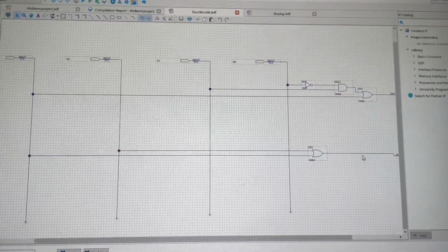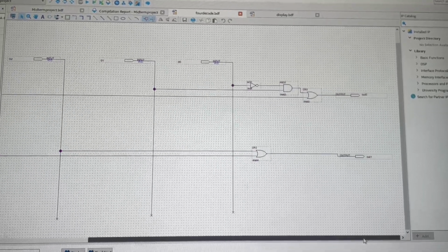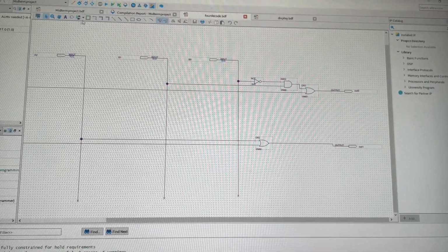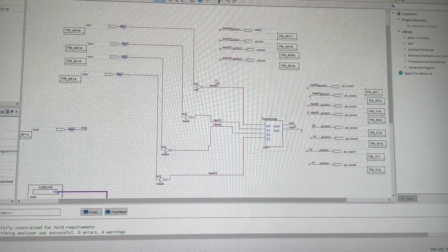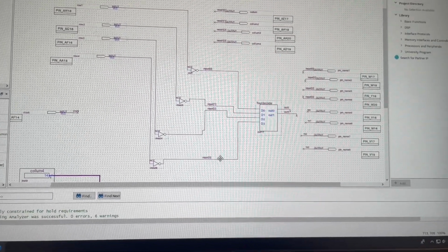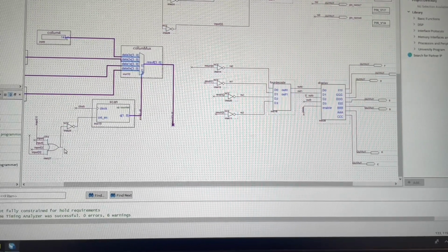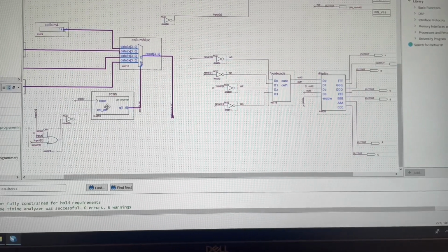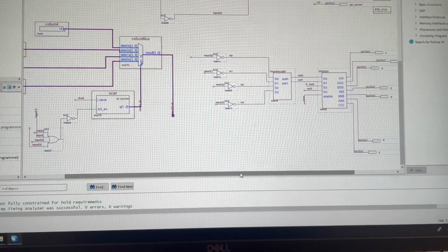As you can see, all the variations will go through, and each of them will create one of those unique 2-bit outputs. Now, this is not the only use for the inputs. As you can see here, when we scroll up, all the inputs are named after their specific NOT gate, and those inputs come down here into a 4-bit OR gate, whose output is named press. Now press is used to stop the scan of the column mux and to enable the display.